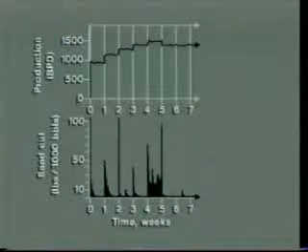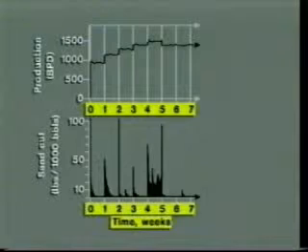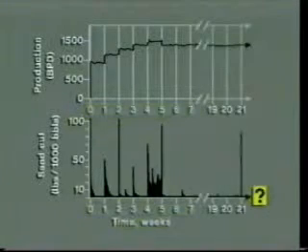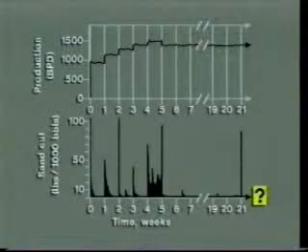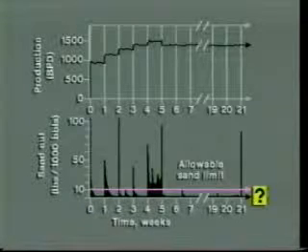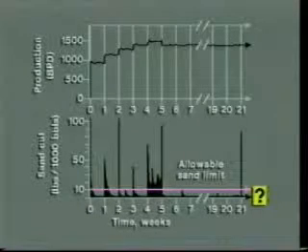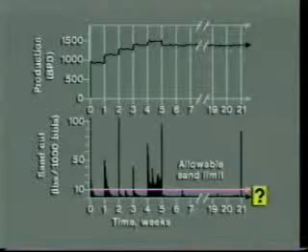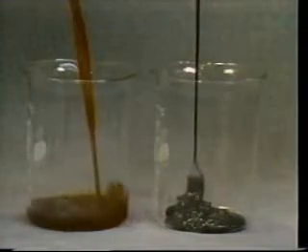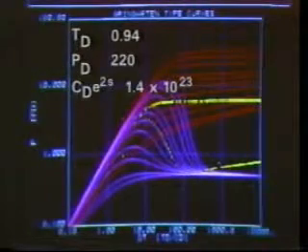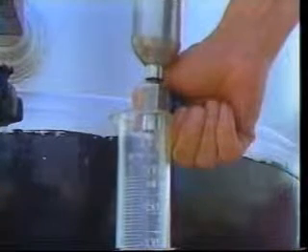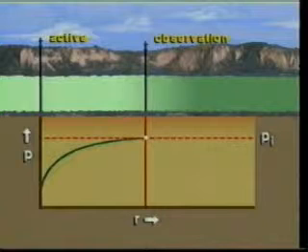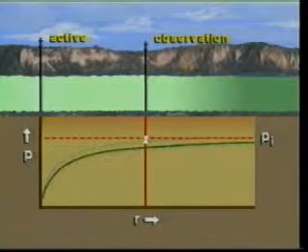Depending on well deliverability and indications of potential sand problems, a step rate production test may last from several days to several weeks. The duration of the test should be sufficient to confirm whether or not the sand influx would persist or decline to an acceptable level without costly sand control measures. During the flow test, excellent data may be obtained about sand production characteristics, produced fluid properties, and pressure transient analysis. You are encouraged to review PE 406, covering the analysis of produced fluids, and PE 401, 402, and 403, regarding pressure transient testing.